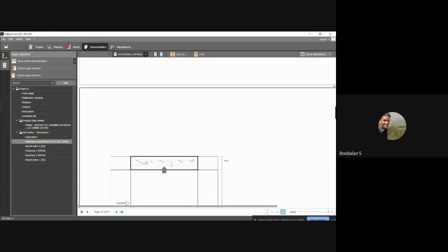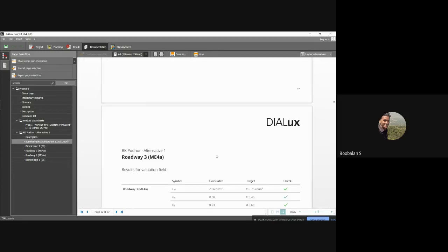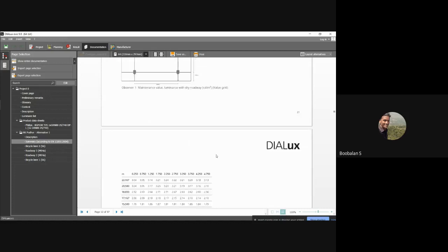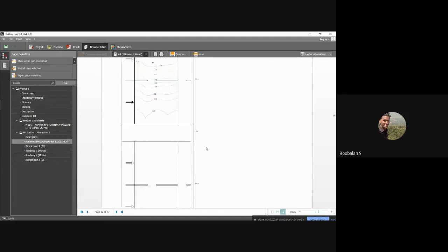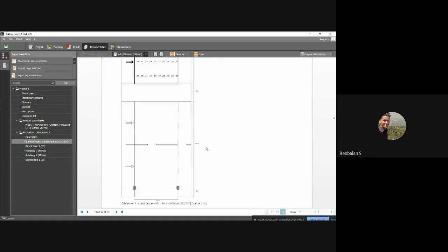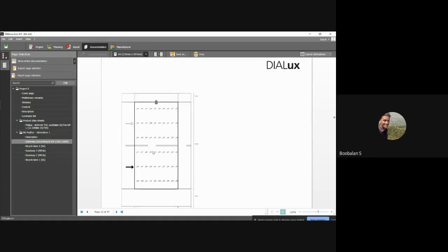As we go further, the intensity of the light keeps decreasing. Now these are the analysis report, entire 57 pages. You could see the meters difference; as we go further, my lumens keep decreasing, the lumens factor keeps decreasing, right? So you could have that graphical view also. Here numerical numbers also will be coming. Near the lamp it is 4.8, and it keeps reducing as we go, it went down to 2.5.